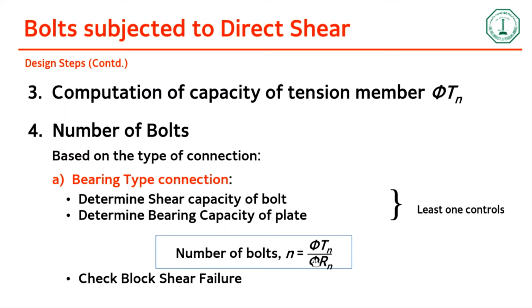In this type of problem we also have to check block shear. You have to make sure that the layout that you have given is sufficient to resist block shear. If block shear fails, you'll have to design the layout again. You'll have to increase the spacing, for example.